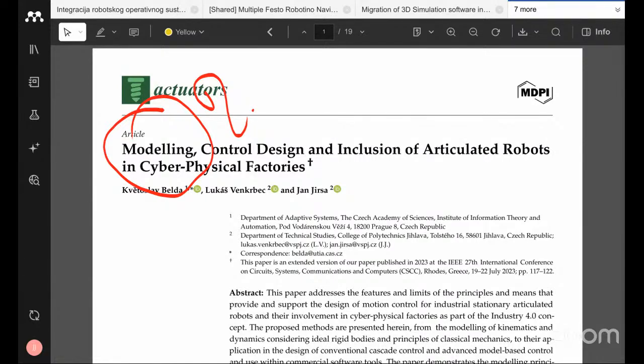So in this paper, they are saying that rapid prototyping means quickly preparing the control algorithms, designing simulation, tuning the parameters, testing this on the hardware, implementing this in the real robot, etc. For that, we can use MATLAB or Simulink, Simscape, Robotics System Toolbox, real-time control toolboxes, etc.